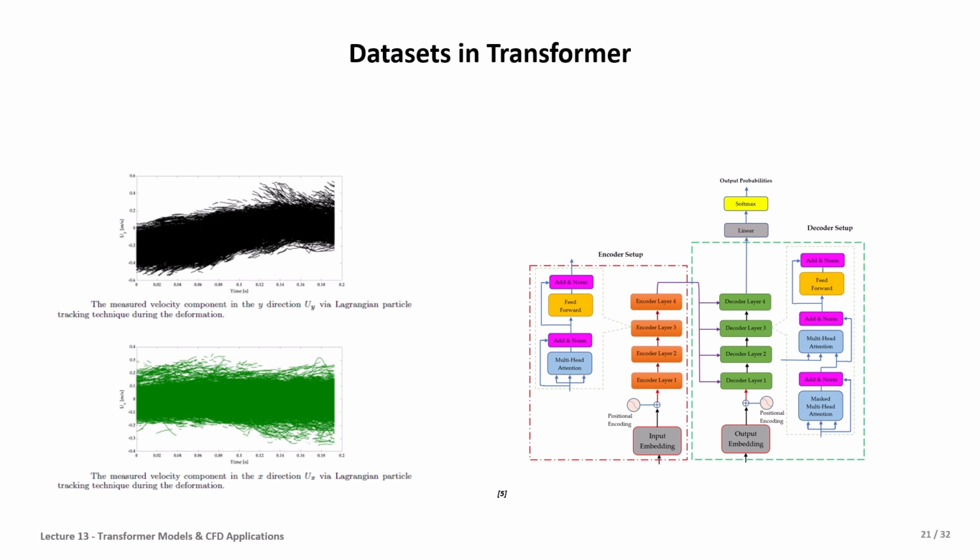I should mention here that this data has two components because the measurement was taken with one high-speed camera, using particle tracking velocimetry or Lagrangian particle tracking, and therefore we have only two components. To capture the information from an experiment with three components, more than two cameras are required to get accurate data, and that is not actually the subject of this research.